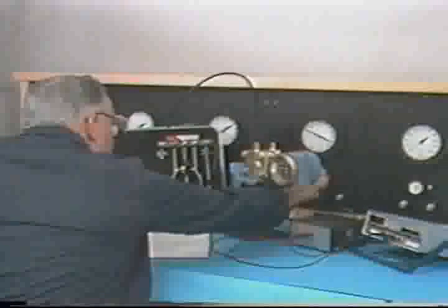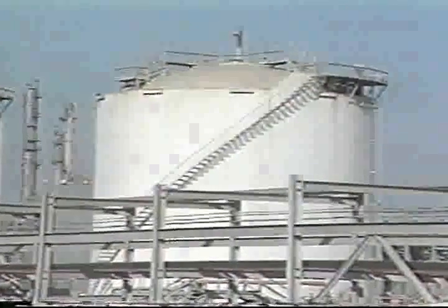Now let's take a look at calibrating a transmitter used to measure liquid in a closed tank, wet leg system. Often, it's necessary to use a reference leg filled with liquid for gauging the level in closed tanks that contain volatile fluid. This setup is called wet leg. This type of system prevents hydrostatic head errors that can sometimes result from the condensation of vapors in a dry leg. A typical wet leg is completely filled with a non-volatile liquid that's stable under normal ambient temperature variations.